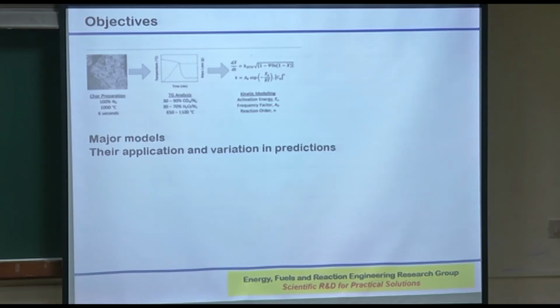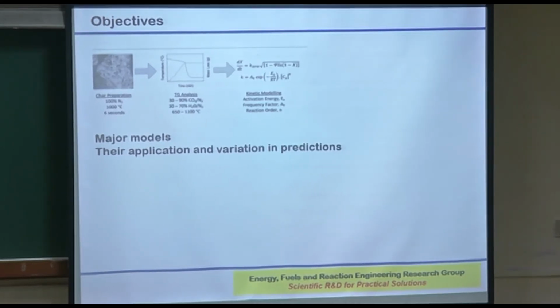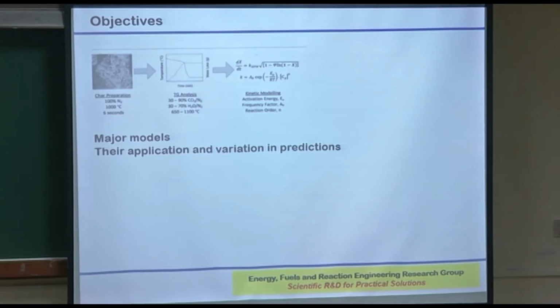Oh yes, okay. So 900 degrees centigrade for 7 minutes. That's for the determination of volatile matter. That's how it is represented or presented in any technique. Yes, that's right. At any temperature you produce the char, some volatiles will be there.